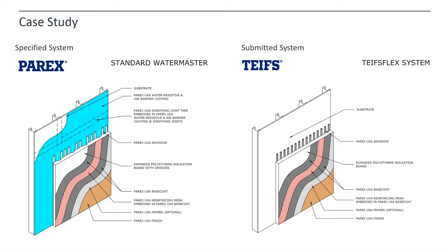I'm sort of intentionally trying to trick you and have you guys think about it. The system on the left does have the vertical drainage channels, and it also shows the notches in the insulation board. Typically with drained EIFS systems, you can accomplish the drainage plane by either of those. You don't necessarily have to have both, and you can look at the ICC-ES reports. You don't always have to have both depending on the system. Sometimes they just say, okay, trowel on those vertical channels and have them go the whole way, and that's it.